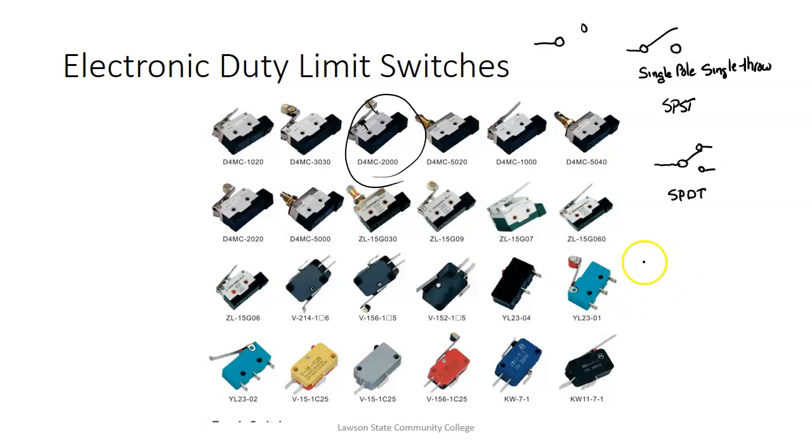So what we would do is we would come over here and we would come in on this one. And then we'd run these two wires. And then over here we would hook this one like this. And then our light bulb would be right there. So right now the light bulb would be off. If I flipped this one up, then the light would come on. I come over and flip it down here, it would go off. If I flip this one down, it would come on. So these are your three-way switches, but they're actually single pole double throws. So that's the circuit on those switches.